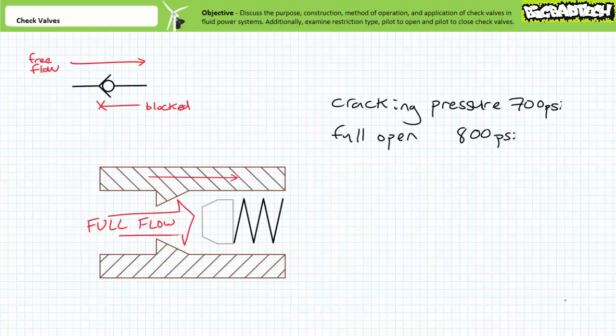Sophisticated, by the way, is a euphemism for more complicated. You'll notice, even for a check valve with a light biasing spring, that unrestricted free flow isn't exactly what I would consider unrestricted, since the poppet still remains in the path of flowing fluid, like one of those large waddling beasts or slowly ambling cell phone users that insist on taking up the center of a narrow hallway or sidewalk in the middle of rush hour. Free-flowing fluid is forced around the poppet, contributing to turbulent flow, resultant pressure drop, heat, noise, and inefficiency.